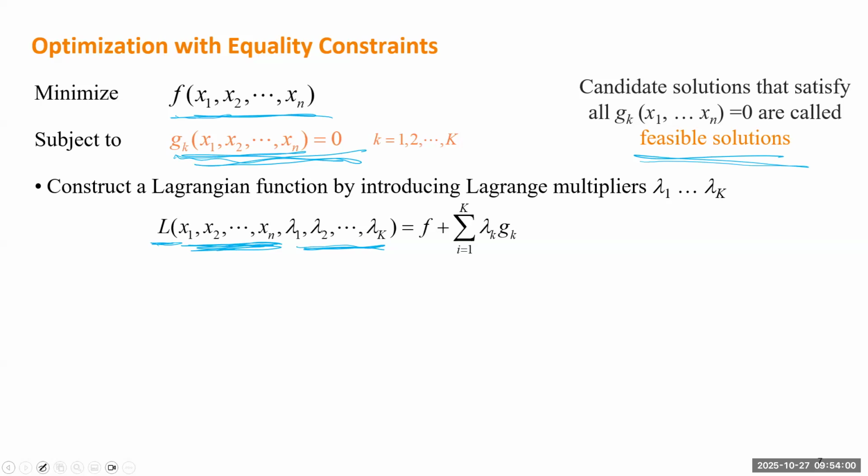If your problem has no constraints, there's no constraint to be violated, so there's no price to pay. You can arbitrarily pick any X value and just determine which is the real local minimum. But once I give you some constraints, could be a power flow equation, if you violate this equation, you're going to pay some price. That price is also a variable to be determined, because there could be some solution where you need to pay a higher price but the overall cost is smaller, right? There could be another solution where you pay a lower price but the overall cost is bigger. So I just gave you the room: you can decide how you want to dispatch generation, and you're also okay to pay some price.